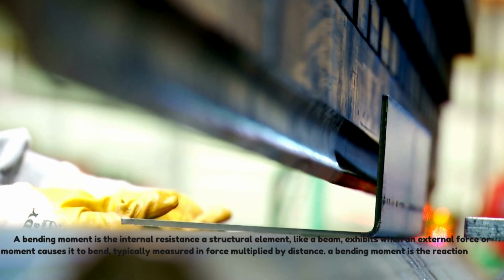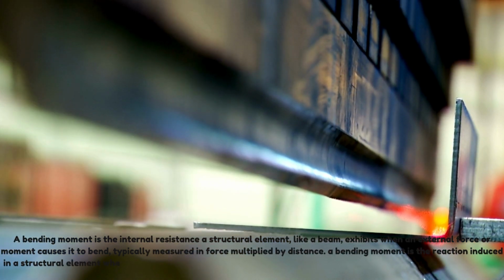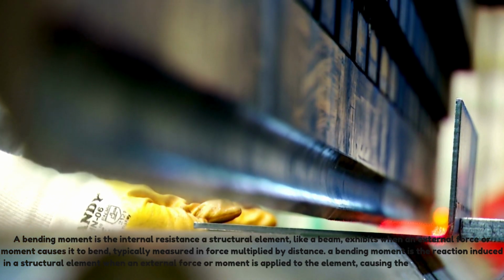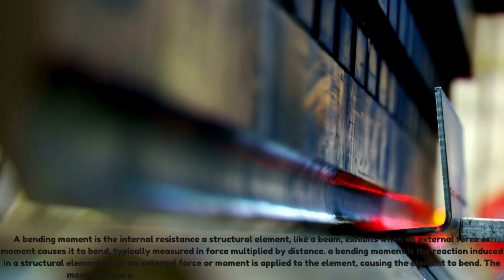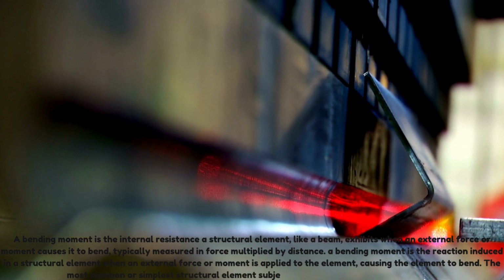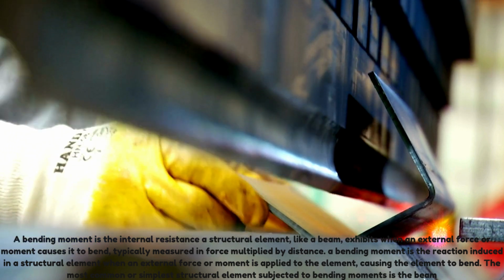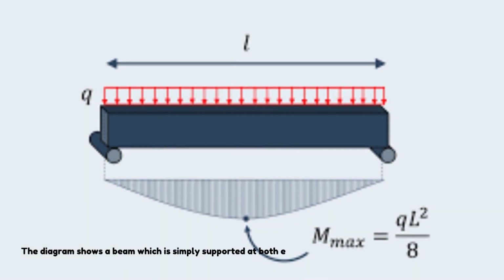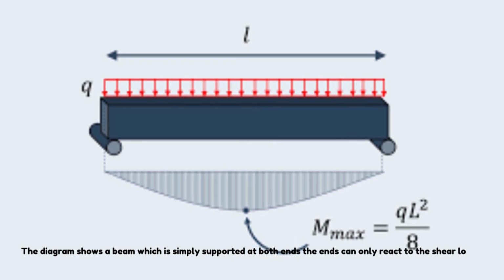A bending moment is the reaction induced in a structural element when an external force or moment is applied to the element, causing the element to bend. The most common or simplest structural element subjected to bending moments is the beam. The diagram shows a beam which is simply supported at both ends. The ends can only react to the shear loads.